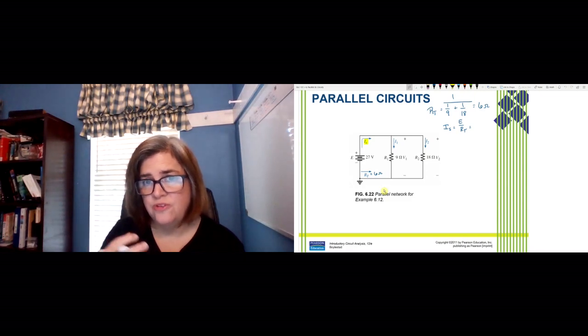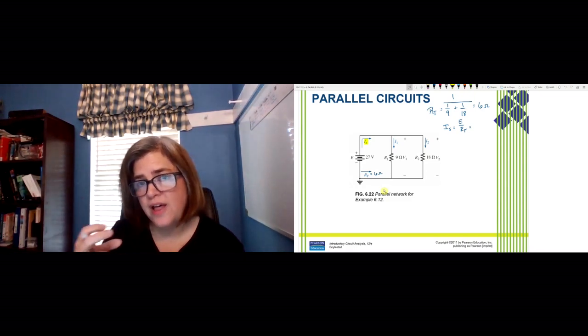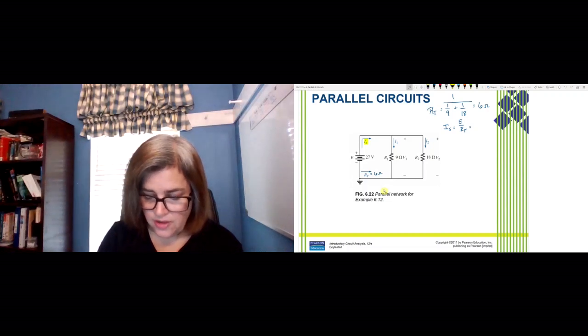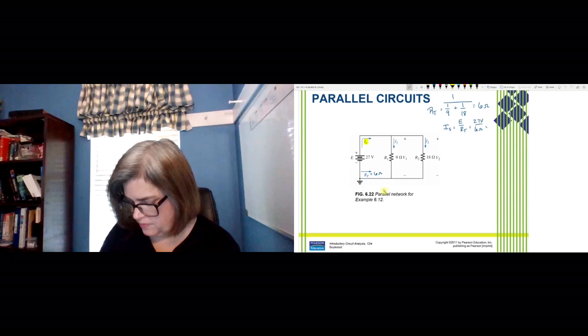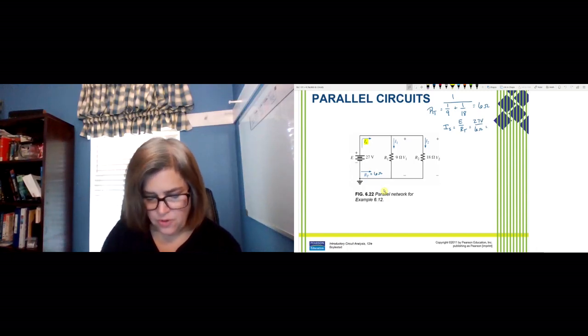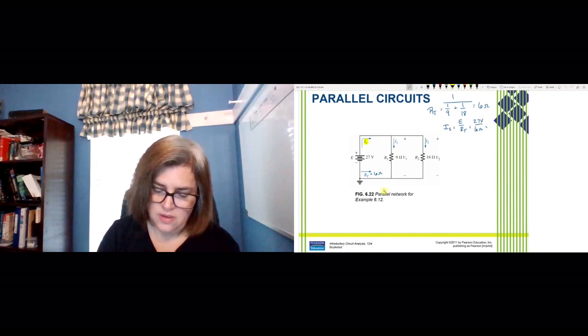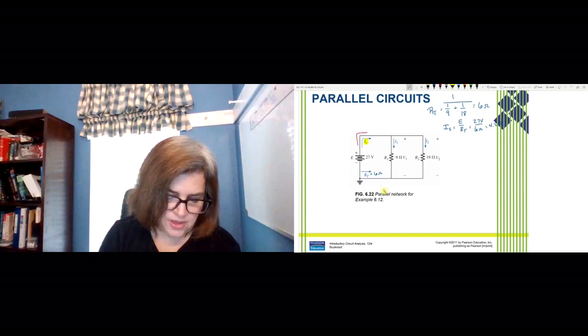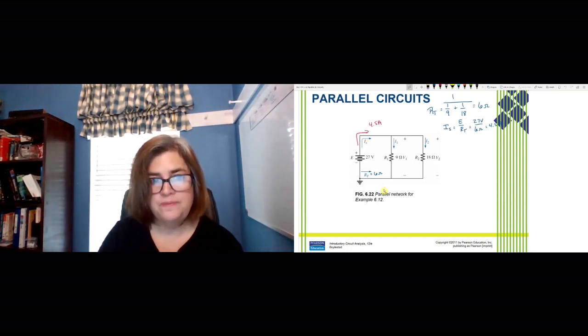The source current is always going to be the total voltage you apply divided by the total resistance of the circuit. So we've got 27 volts there divided by 6 ohms. So that gives us about 4.5 amperes of current there. Okay, so if I draw that in, that means that we're supplying 4.5 amps of current to the circuit.